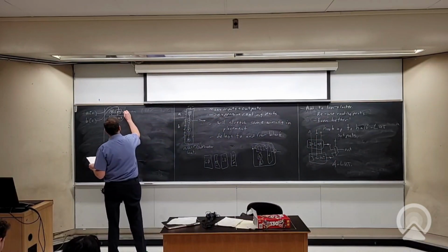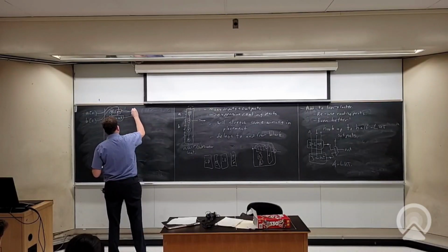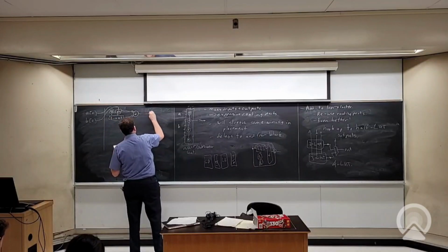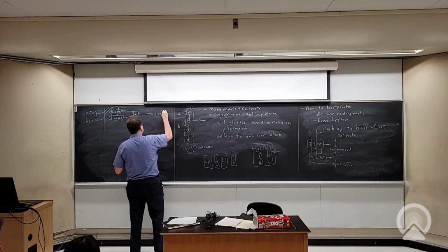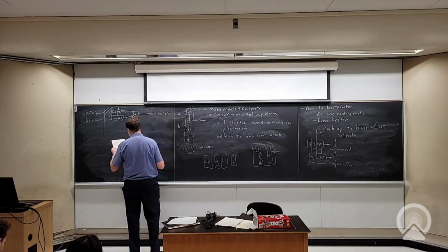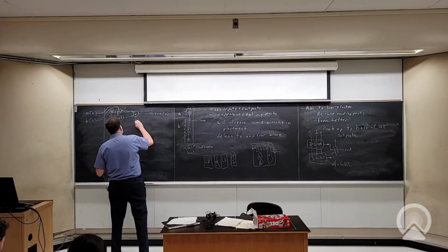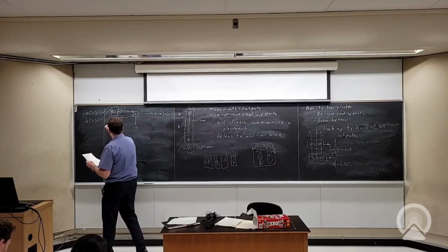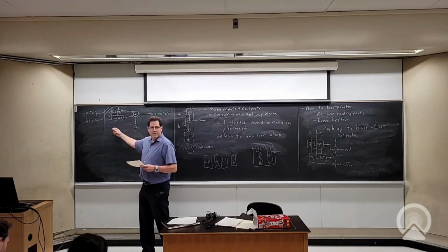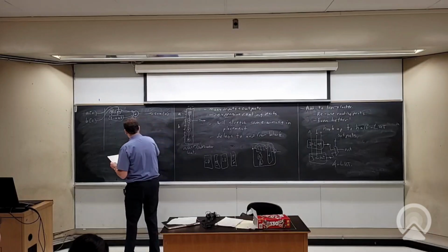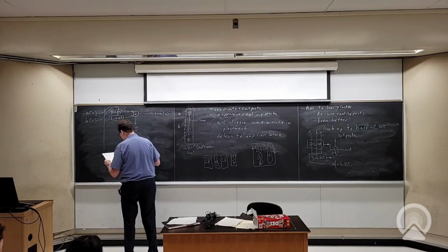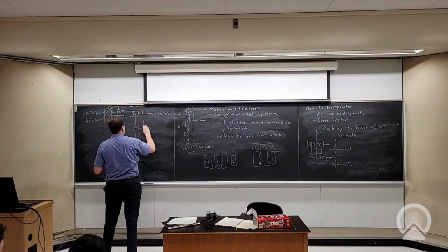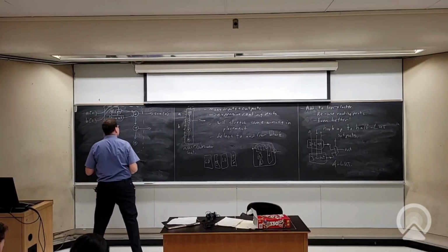And I take those 2 outputs and I put them into a full adder and produce a sum output. And then I also take the carry out of that and I send it to the next adder, and I'll have LUTs in front of it and B of 1 and A of 1 and so on. And this goes down to the next adder and so on, right? So this whole thing is my new logic block with a carry chain inside of it.